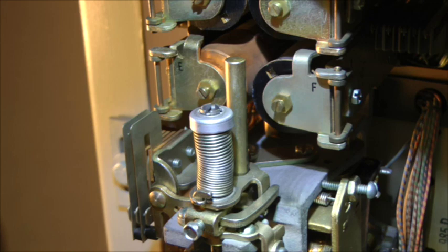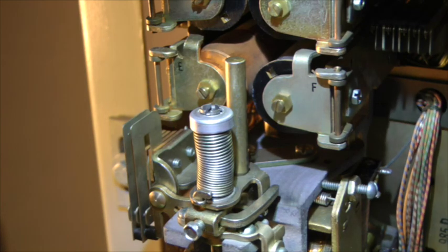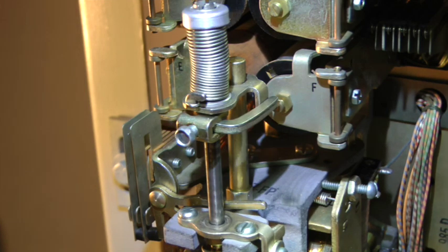The top of the spring is attached to the cap. The cap is fixed to the shaft, and so it rotates with the shaft. The bottom of the spring is attached to the shaft spring bracket. The shaft fits through a hole in the shaft spring bracket, but the bracket is not affixed to the shaft. The bracket simply rests on a clamp, but the clamp itself is affixed to the shaft. So when the shaft steps vertically, the spring assembly moves up with the shaft.